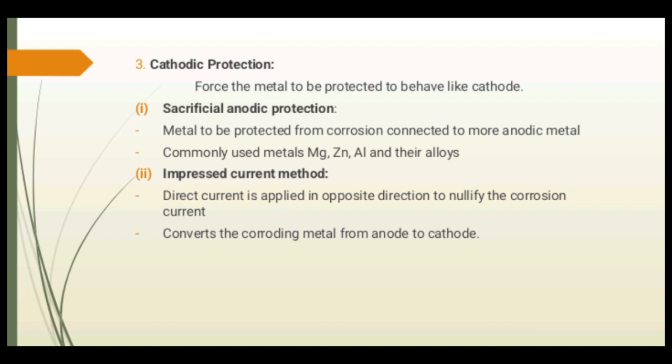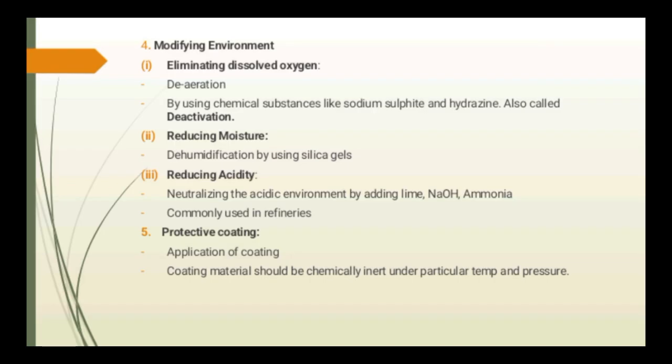Cathodic protection is a widely used method to prevent corrosion, and it involves forcing the metal to act as a cathode. This can be achieved through sacrificial anodes or impressed current systems. Organic inhibitors like amines, mercaptans, urea, and thiourea reduce H ion diffusion by adsorption. Next is modifying the environment or metallic coating. There are hot dipping, metal cladding, electroplating, and electroless plating.